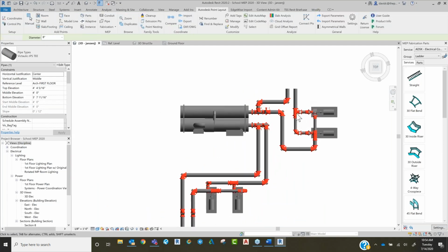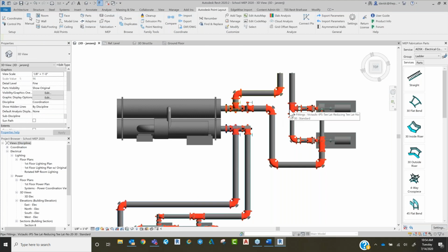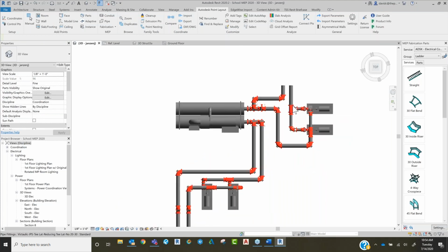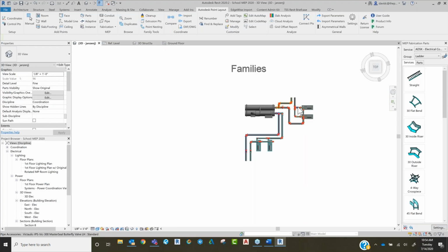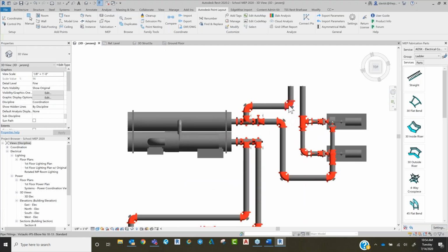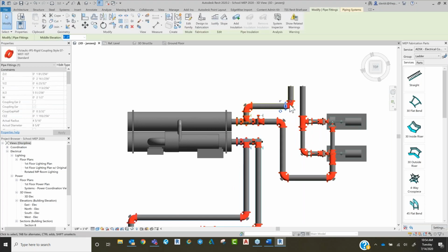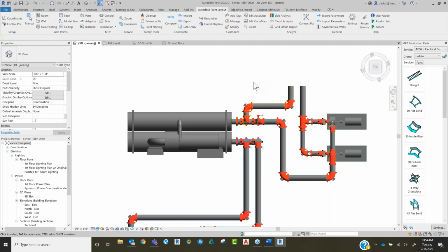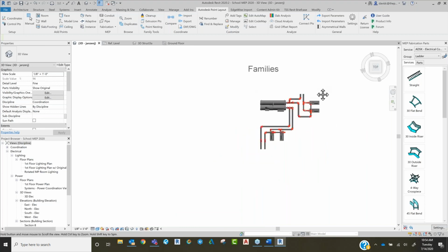Now, in here, some of my connections wouldn't have points because these are essentially like a Revit family, okay? These are Victaulic series, but we can use several different types of families that have a lot of different parameters that we may bring in from a manufacturer, and we can utilize layout to still lay out with these parts or these pipes.